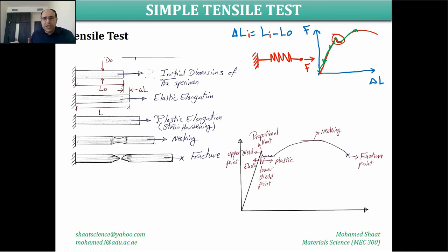What distinguishes is that within the elastic region or the elastic limit, the material can restore back again to its original dimensions and shape upon the removal of the force. But in the plastic region, if we try to remove the force, the material cannot restore back to its original shape and dimension, and instead the material will show a permanent change in the shape and the dimension, which cannot be restored back one more time.